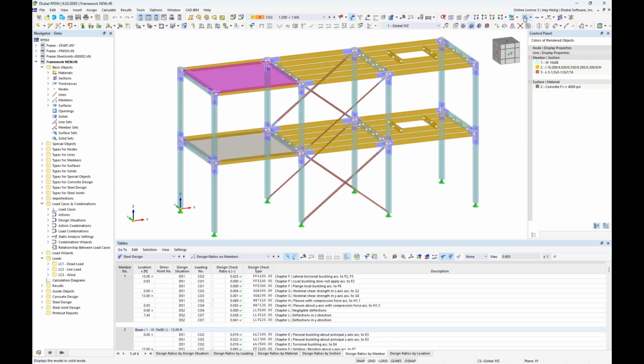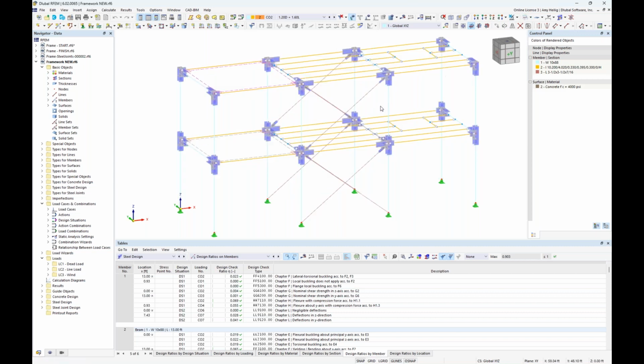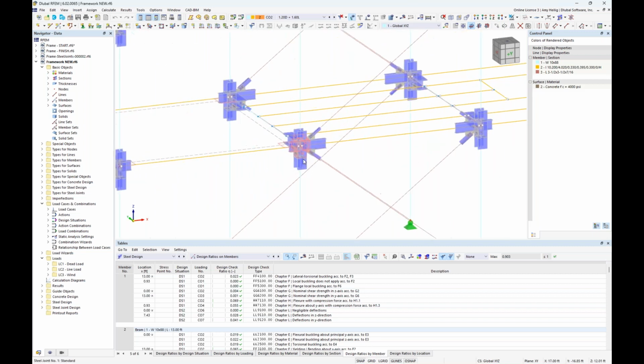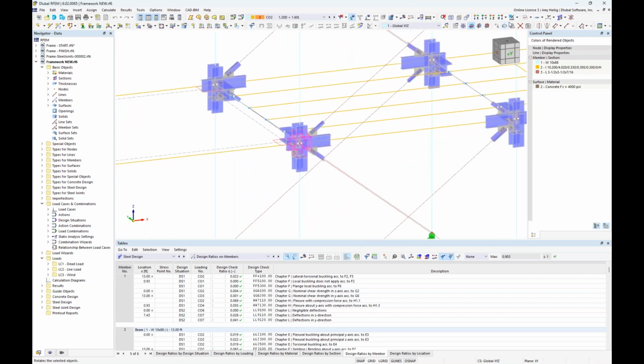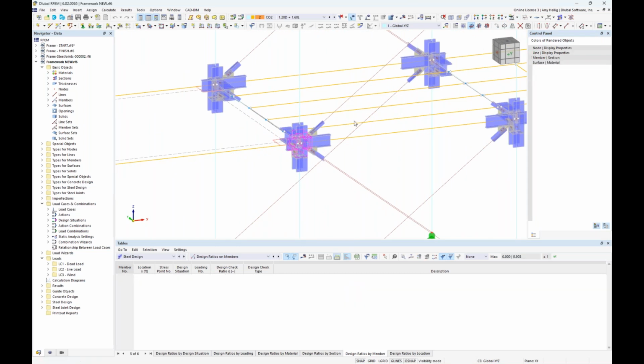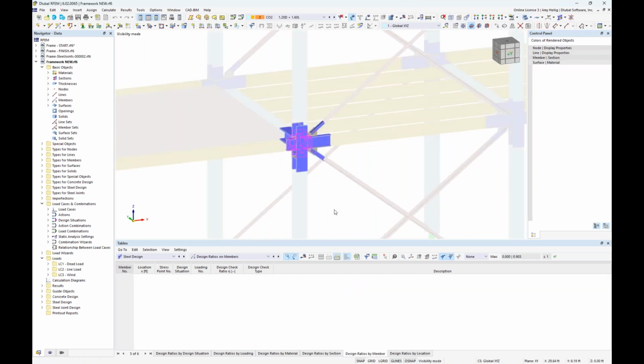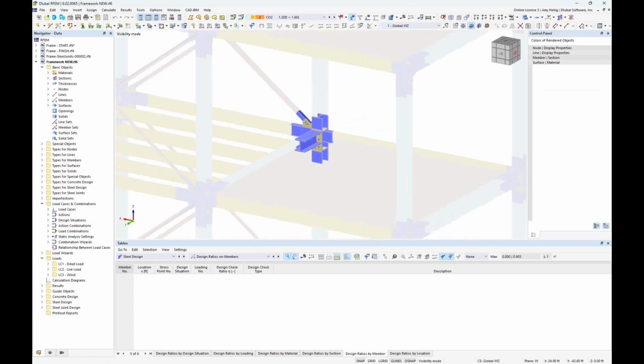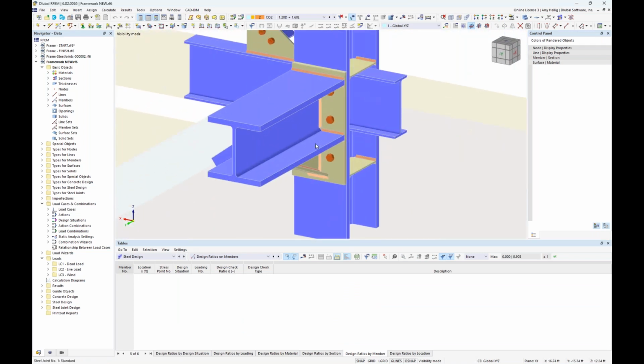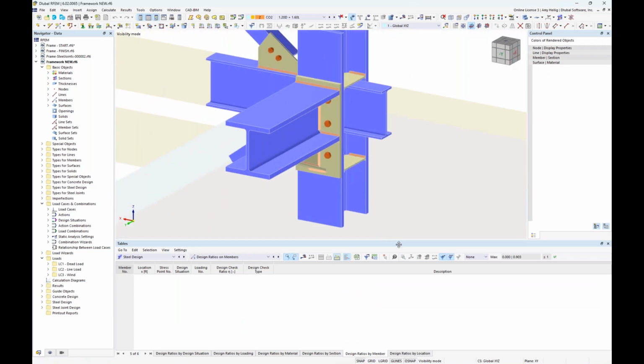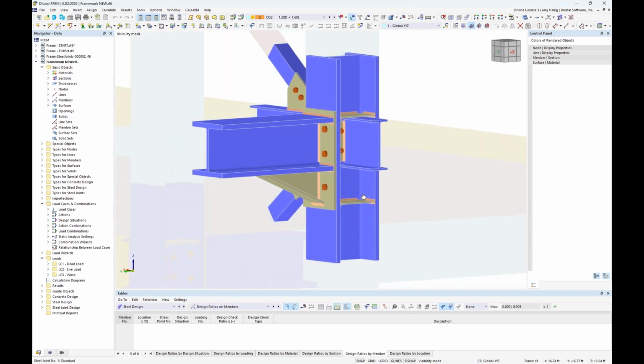And if I go to the wireframe view, what you'll also notice is that I have defined these joint connections at all of the major intersections here of our steel members. So if we take a look at maybe one of these particular connections, I'll go ahead and create a visibility by this selected object. And let me turn this back into a solid rendered view. Well, when we zoom in here, we can see that this connection is certainly a little bit more complex than what we just saw with our 2D frame.